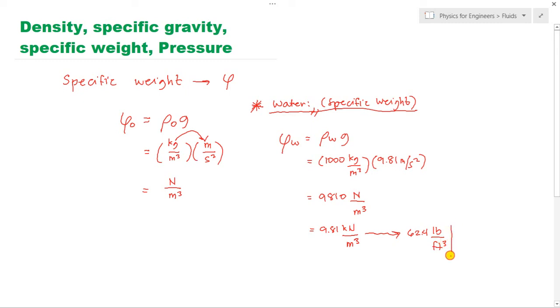So those are the constants you need to remember, because they are used when we are answering problems in fluid dynamics. So again, your task is to prove that the equivalent specific weight for water in the English system is 62.4 pound per cubic feet. It's actually just a conversion, class. Okay, how about for air?